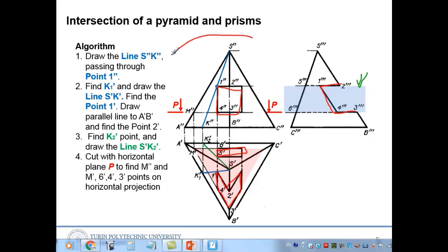First, in this view, we have to make the dots, the points in the corners: first corner, second corner. We are selecting only one half, as the other half is symmetric. So the first point is here, the second point is here, the third one is here, and point 4 is here. By using these 4 points, we can get the projections in different views, okay?